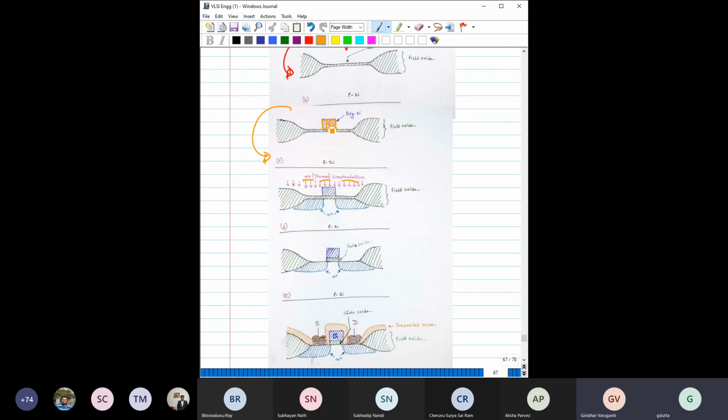This is polysilicon, which is nothing but polycrystalline silicon. Okay, this is crystalline silicon, this is crystalline silicon, this is polycrystalline silicon. That is the thing. Polycrystalline means its orientation is, say, if I say this orientation is 100, then the orientation of the crystal is fixed here. But for this polycrystalline, there might be many orientations inside these regions. It may be 100 in some region, 110 in some region, maybe 111, like that. So that is what a polysilicon is.